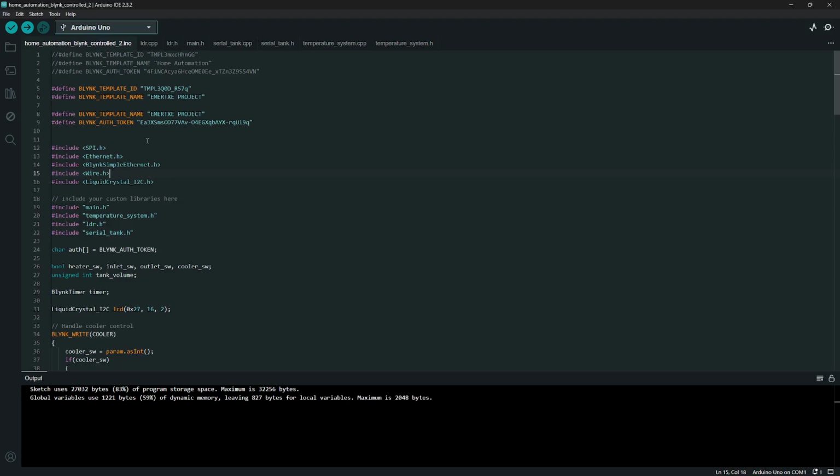So how would the devices know that we have sent a command to them and they can act upon it? For this project, we have downloaded the Blynk IoT application from the Play Store on our phones, and we have configured some buttons and set up some virtual pins for each and every button.